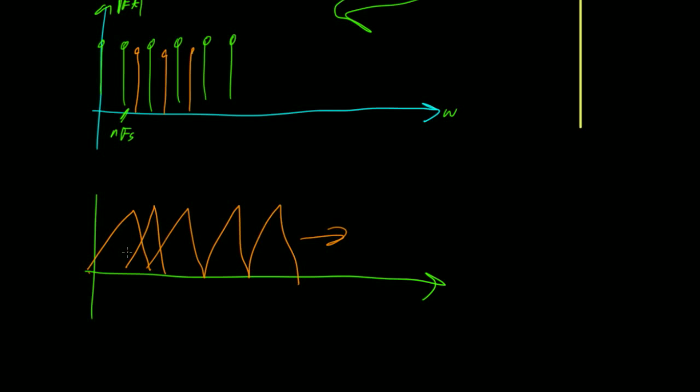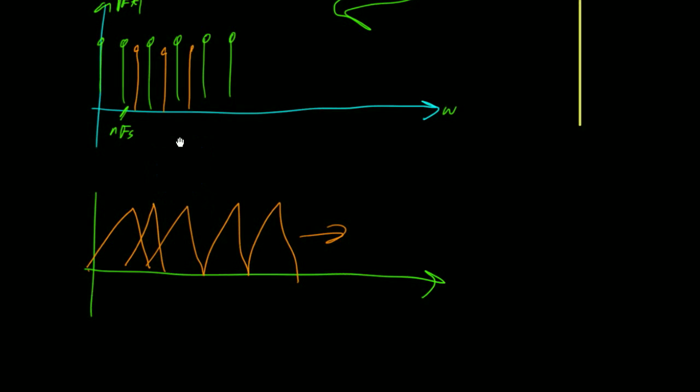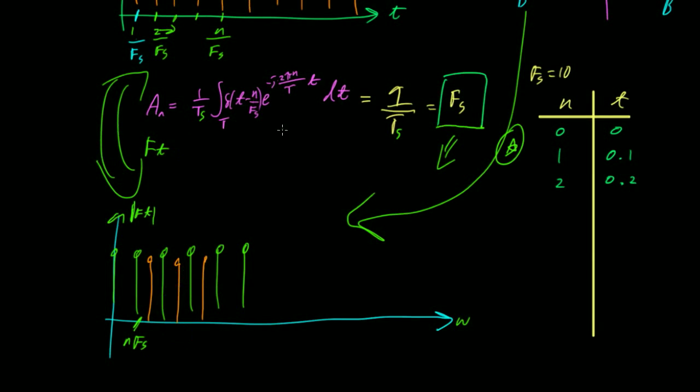I've gotta say, that seems kind of contrary to what we previously learned when we had an impulse in the time domain be a constant. That's because you weren't looking at a periodic signal. Before, when you did the Fourier transform, it's the same thing minus the 1 over T, and you only had one impulse. You know what I'm saying? So that's why it goes to a constant.